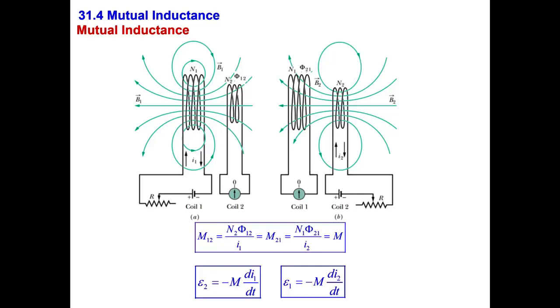So if you have, for example, a power line of 220 volts, and you need only 10 volts, you can use a transformer. The power cord is connected to the power line, to the primary coil. So you have the high voltage, and you have a step-down transformer, so you bring the voltage down to 10 volts because your circuit is operating between, for example, 0 and 10 volts. So this is the principle of the transformer. It operates on the principle of mutual inductance.